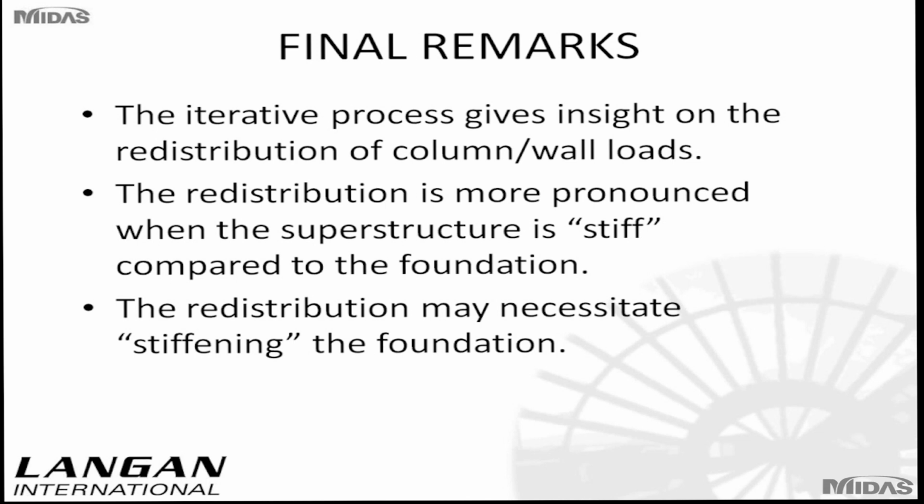So if you see that this redistribution is causing too much stress on the walls, you may want to stiffen the foundation, and to do that, you may choose to add more piles and/or take the piles to a deeper stratum or elongate them.